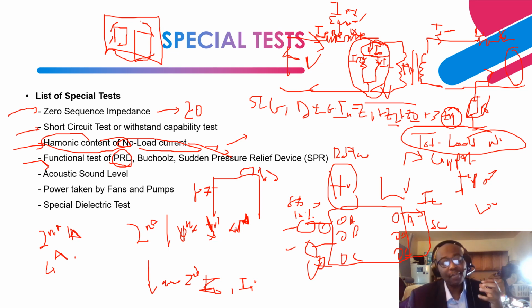If the differential relay should fail, then you have a backup protection 50-51 relay that will pick up and trip the transformer. On the other hand, you have the 63 sudden pressure relay that can be the first-line protection scheme for the transformer if the differential current has not developed enough current for the differential relay.